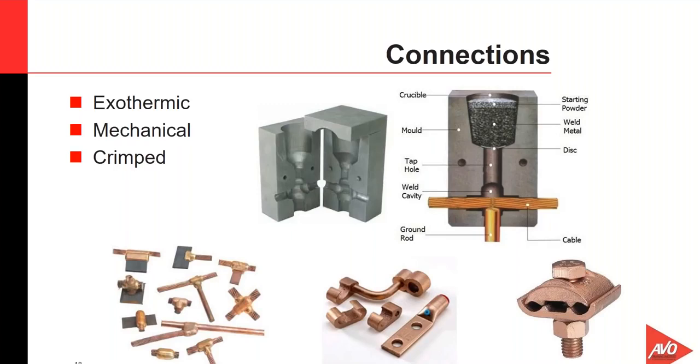What this is telling us is that we take the metal oxide and aluminum, heat it inside, and it causes an exothermic process, a welding process that sends the molten metal down through the mold to the bottom part. This is a T type of exothermic connection, connecting these three conductors in a welding process.